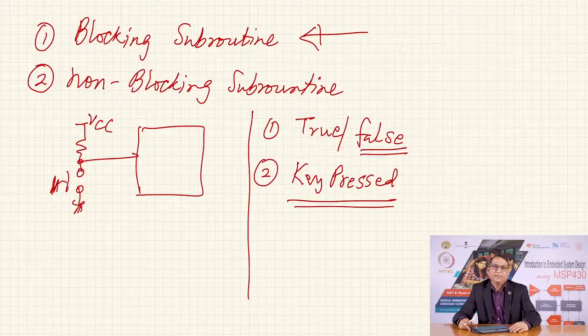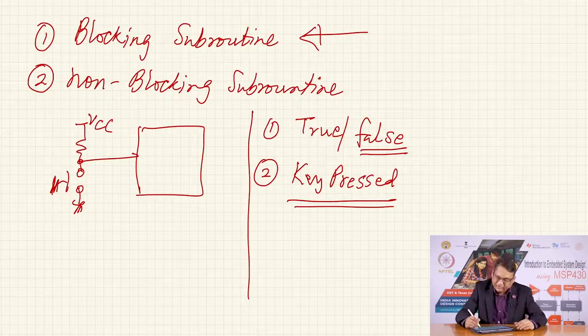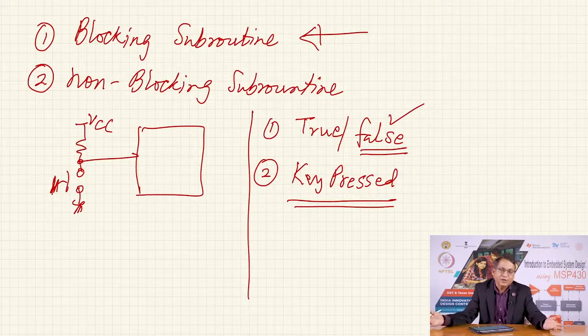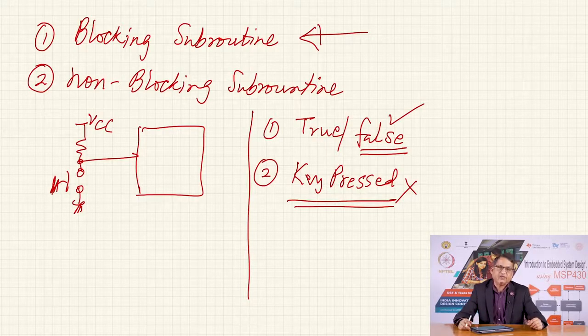He or she programmed the switch matrix and wrote the subroutine as a non-blocking function. So, if you did not press the switch within a stipulated amount of time, it will go back to the main program with the return value set to false, meaning there was a timeout, nobody pressed the switch, and the main program will not look at the second variable.